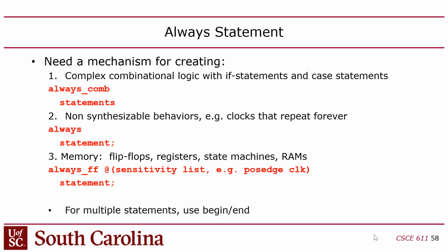When you do your lab 2, that's going to be combinational because you're just going to flip switches and the hex displays are going to update immediately. So you don't need any memory in the design for lab 2. Of course, when we get to the CPU, we're going to have to add memory. That'll be sequential because we need an instruction RAM and pipeline registers and so forth. Make sense?